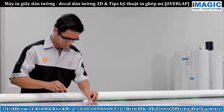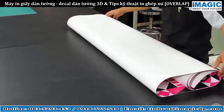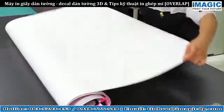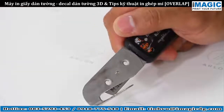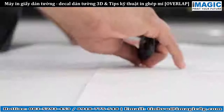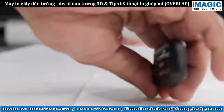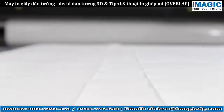Repeat this process on all panels. Using a release liner knife, cut a 2-inch strip in the liner approximately 6 inches away from the top edge on each tile. Leave this liner strip in place.